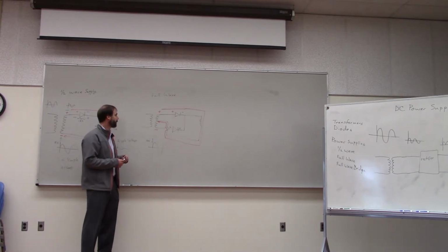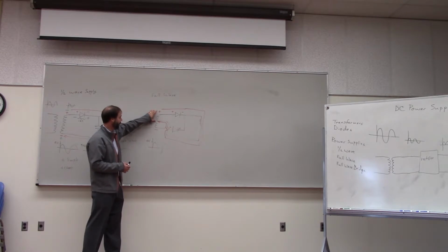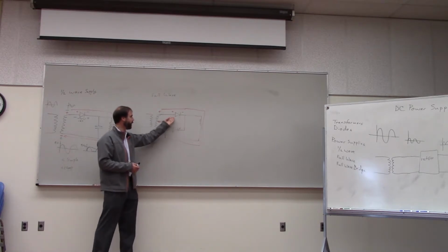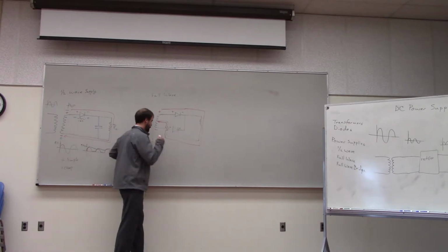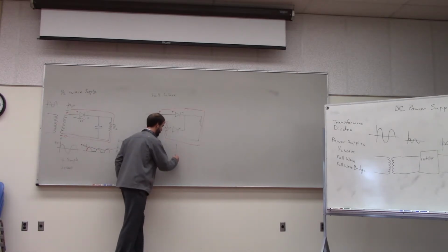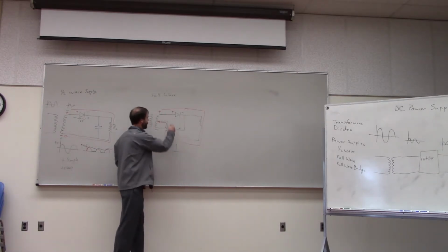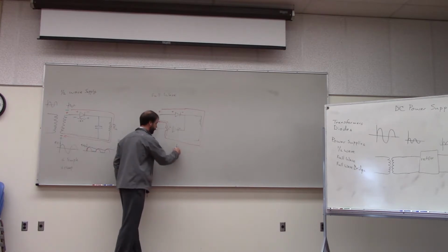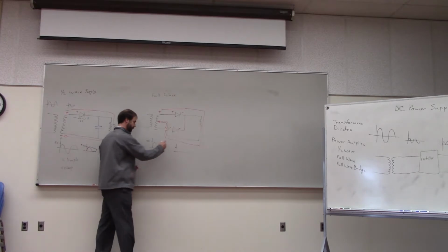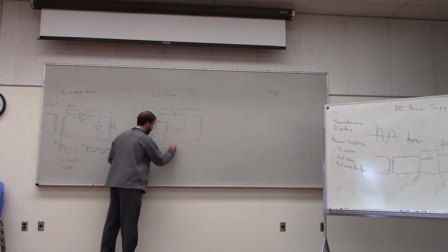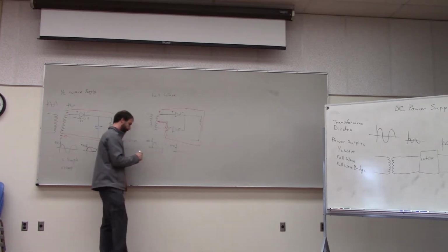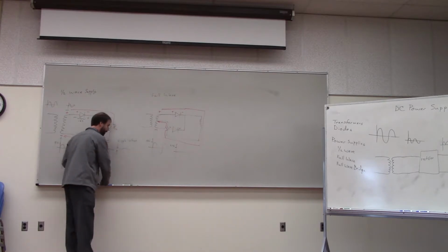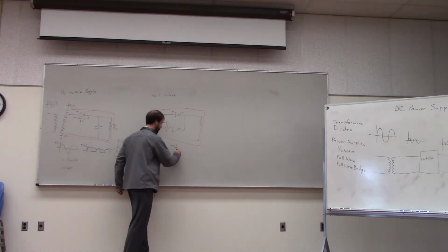So we would have half there, and we're still going through one diode, so we're really getting an output voltage which is 5 volts minus 0.6. So what is the peak of the output voltage going to be? 4.4. Exactly, 4.4 volts. So we have a positive pump of 4.4 there.